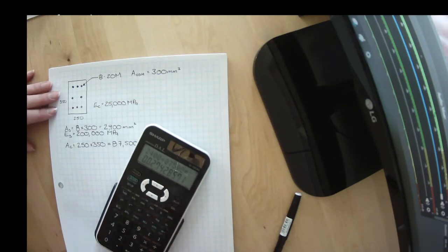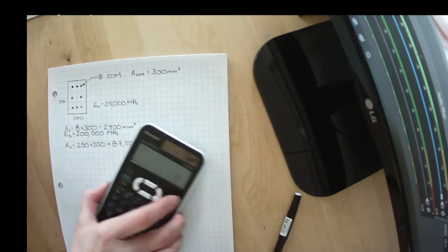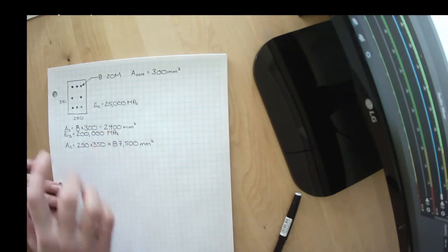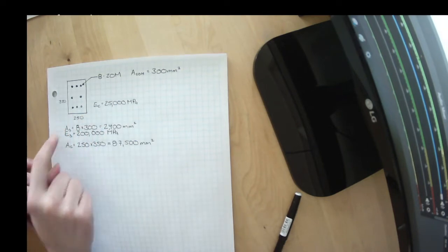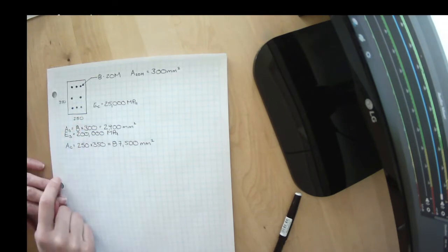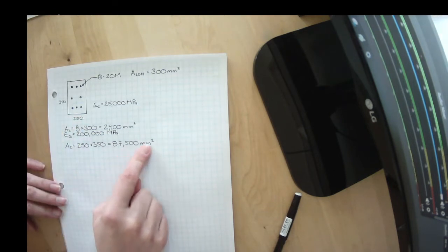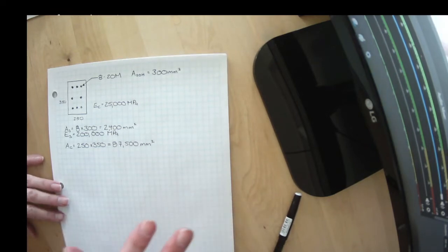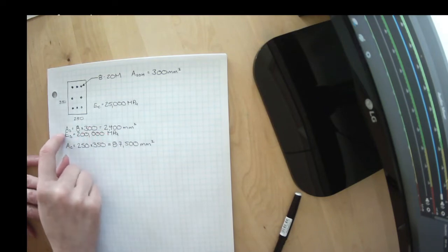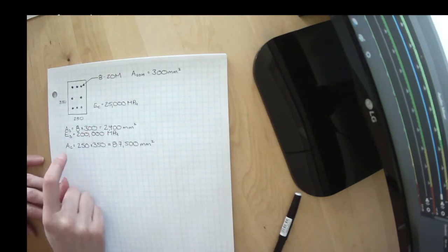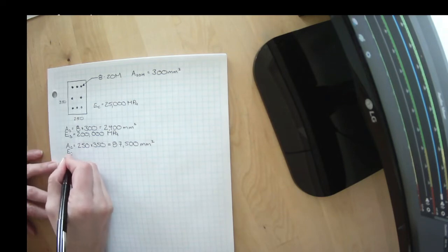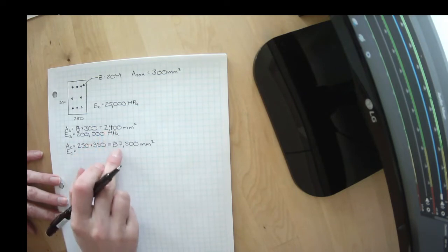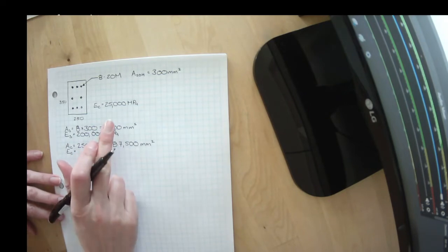It's like removing about 2.5% of the concrete area. For the steel, 2,400 is 100% of its equivalent area, or its importance of area. For the concrete, it's only 3% of its area, or somewhere less than 3%. So that 2,400 is much more significant to the steel than it is to the concrete. So we are not going to remove the area of the steel from the area of the concrete when we're talking about rebar.